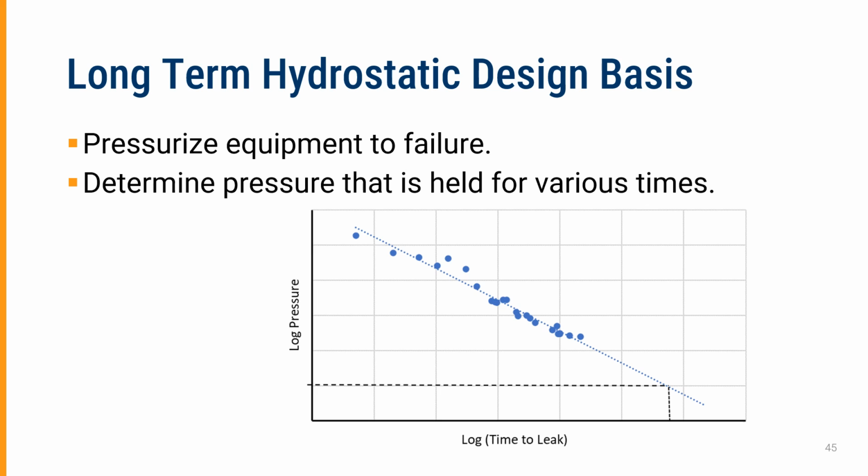And in fact, in order to come up with the design basis for a particular time, you find what time that is, or the logarithm of the required time, find this curve, plot back, and you can say that is the maximum pressure that it should be exposed to for that. This is very specific for a single design set of materials and construction.